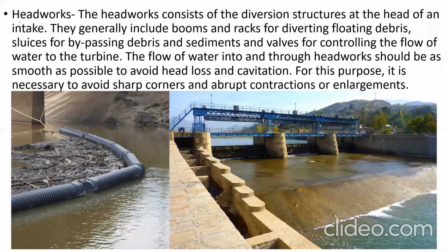Okay, take it. Next is the headworks. Headworks means what? A lot of debris comes to the reservoir when water comes from the hilly areas. Debris like wood, plants, leaves, or any floating material which flows on the water has to be removed from the reservoir, else it will hamper the operation of the turbine, or the turbine may get damaged. For that, headworks is done.